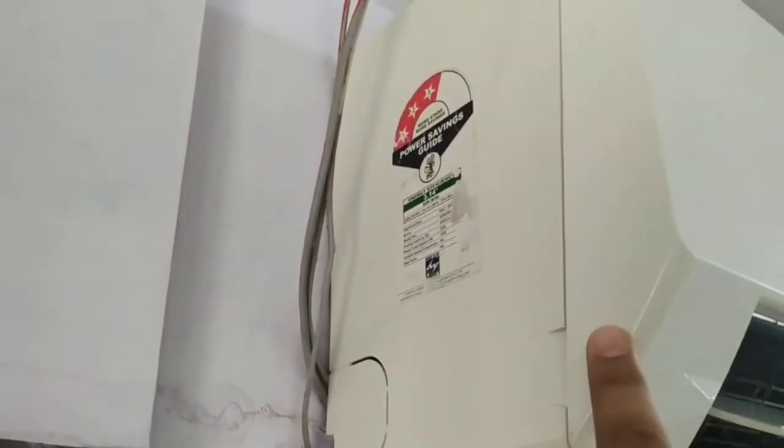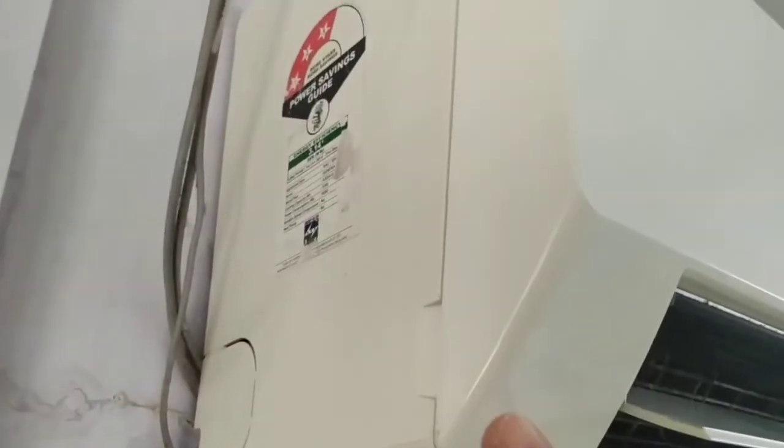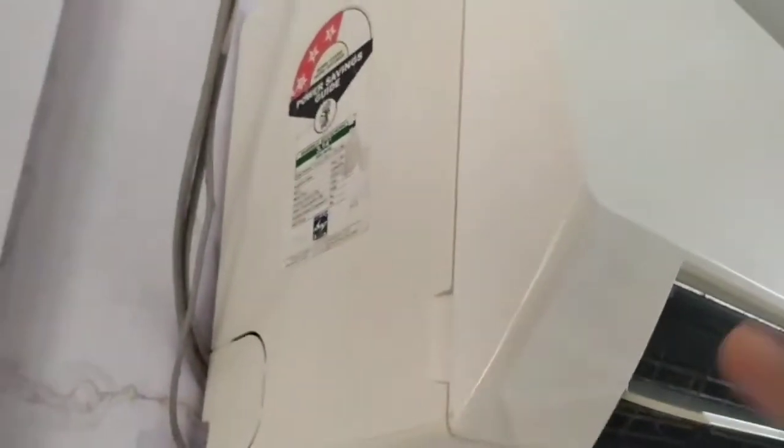So as you can see here, the wires bring in current here. What if the plastic coating is damaged and it comes in contact with this metal case, or even if there is a metal case inside this plastic, and if you touch it, then the current can pass through your finger and you can get a shock. But there is some earthing connected inside, which is not visible here, and that earthing is connected to the earthing wire of this house, and many such equipments of the house are connected to the same local earthing.